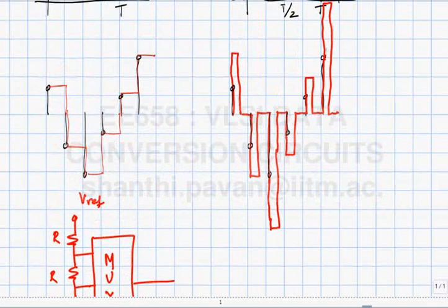The bottom line is basically that while we analyze the whole system assuming a Dirac delta train going into a filter with a sinc-type impulse response and frequency response, definitely that's not how it's going to be. That's what you use to analyze, but that's not what you use to implement.